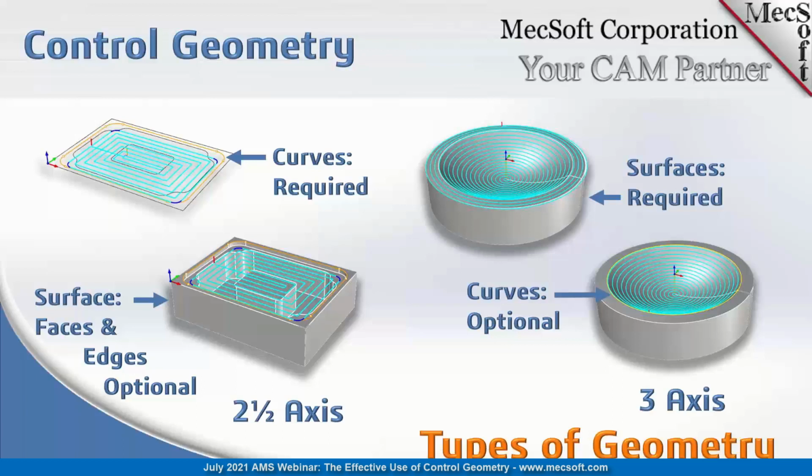If you try to perform a 3-axis operation with no surface geometry, it'll tell you you can't do it because you don't have any geometry. So you've got to have surfaces. It can be one surface, and we've got a great example of that we're going to show you in a moment, or it can be a completely closed 3D solid model, whichever, but you have to have surfaces. And in 3-axis, the curves are actually optional. You can use your control geometry selections to contain your 3-axis toolpaths.